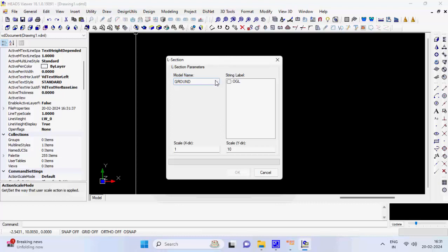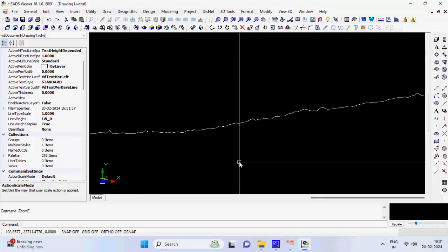The polyline should pass as close as possible to the ground tunnel bottom center line. The points should be sufficiently away from each other to accommodate curves to be set at this point. These points are called vertical intersection points, VIP.